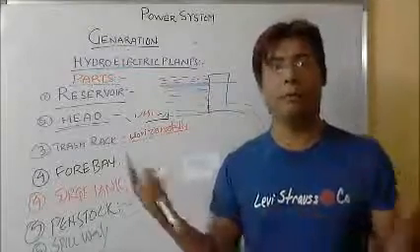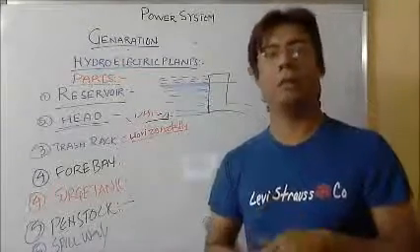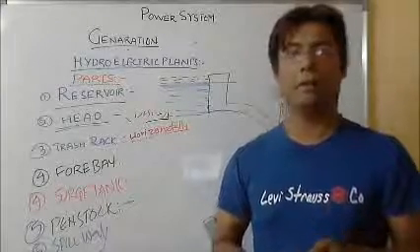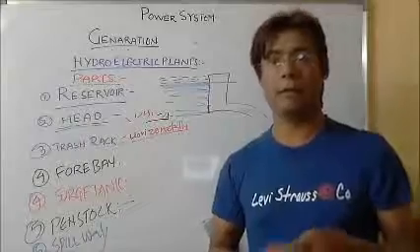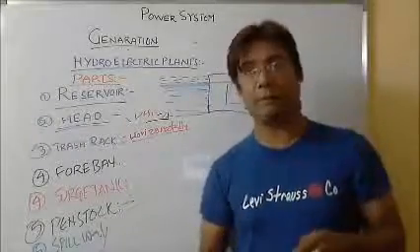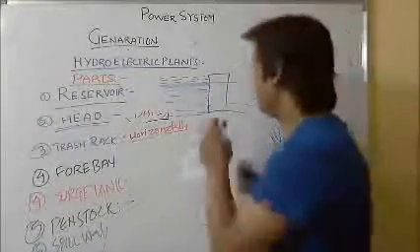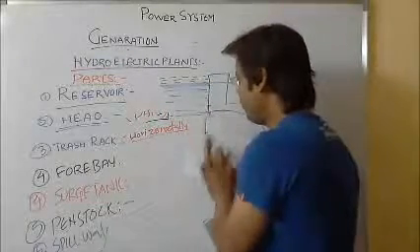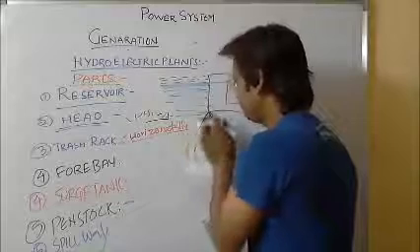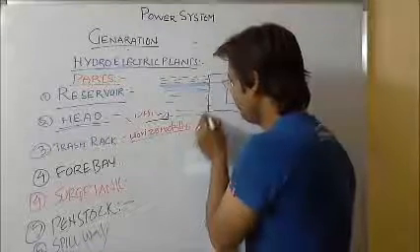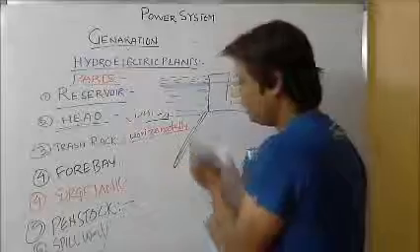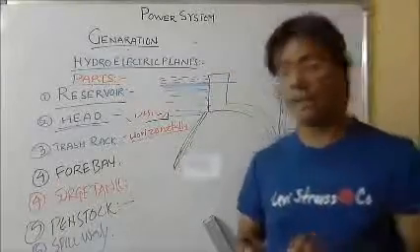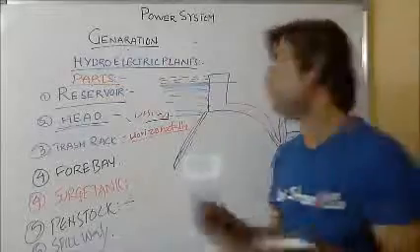If the dam collapses, the huge water will flow over approximately 100 kilometers or more and disturb the living environment over there. So that is very hazardous. For that, one more arrangement is there: when the water is more, there is a spillway before the intake of the water here, such that the extra water goes into the spillway, and it works as the safety valve for the dam.